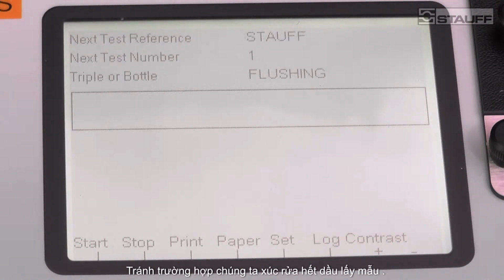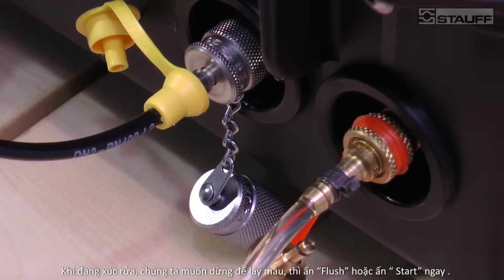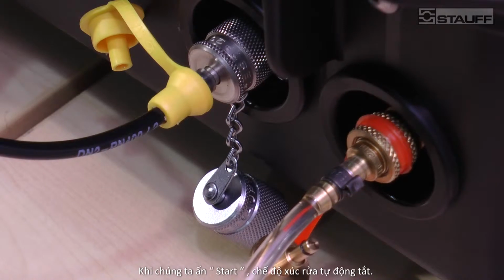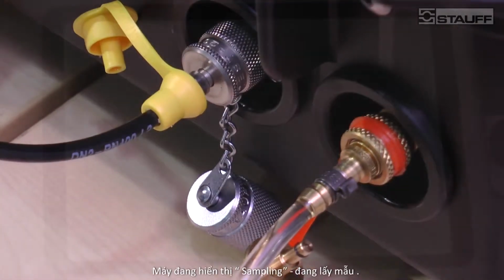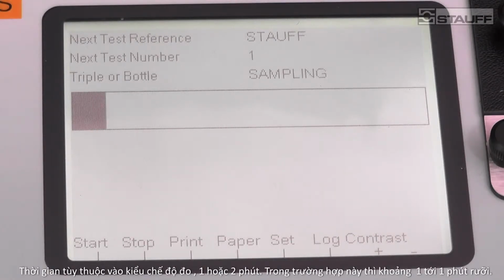So now we've flushed the particle counter, we can press the flush button to turn it off, or we can immediately press start. When you press start, the valve automatically closes. So now the machine shows us sampling, and the progress bar also indicates the progress of the sampling. This process usually takes about a minute or two, depending on the type of test, but in this case it's about 1 minute or 1.5 minutes.